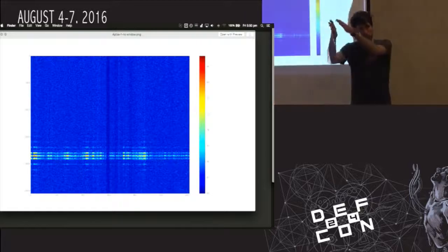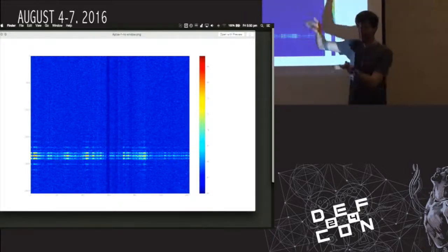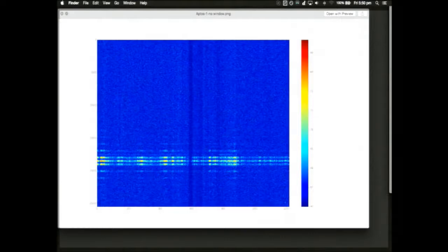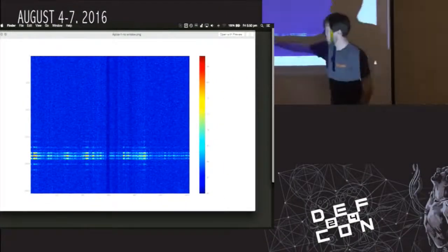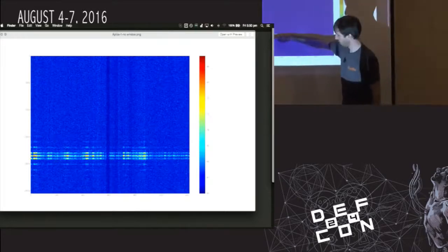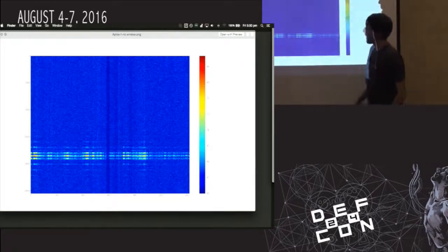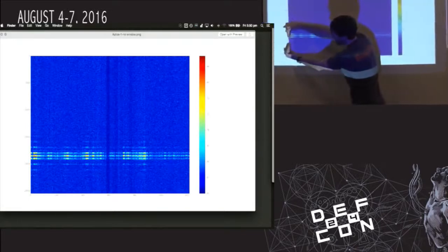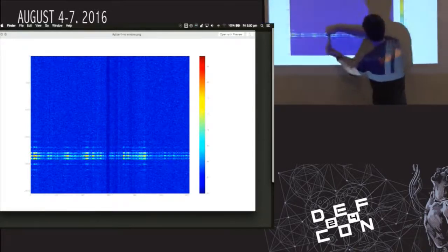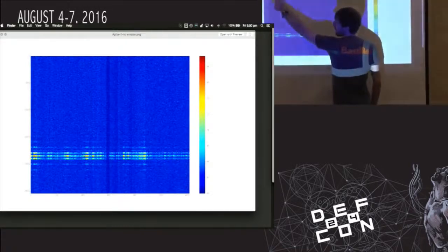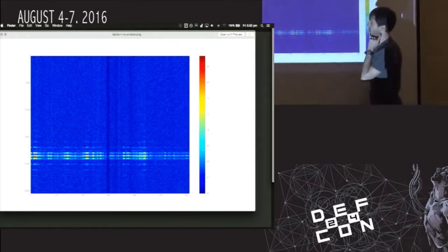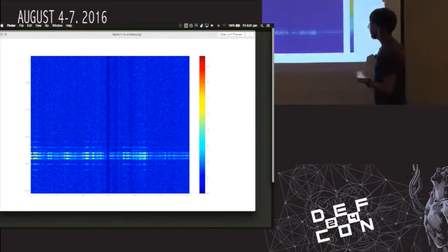Remember how we had the AM-ing effect and we had those side lobes? Because you have that frequency that's chirping down, going from high frequency to low frequency. If you match that with your own chirp and you mix it down, you then get a straight line. So that main lobe then just becomes this straight line here, and then we have the other side lobes that come off there. And the way this is running is this is actually an FFT that's running from left to right. So this is time here, and each FFT is the length in terms of samples of one chirp, and that's how you can produce these nice plots.